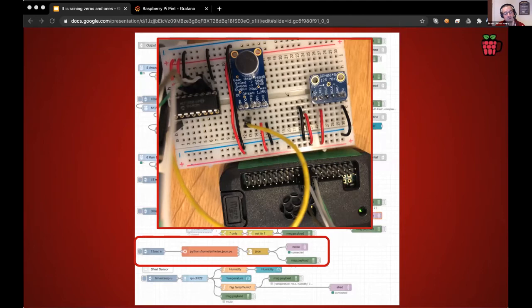But after banging my head with this for a couple of days, I reminded myself that actually I'd been doing some NeoPixel stuff with this Pi just before I started building the weather station. So I grabbed my Pi Zero, initialized that, flashed it, made it all work. I was like, okay, right. So that's what's gone on there, because having been using pin 18 for the NeoPixels, it messed around with what was going on there.